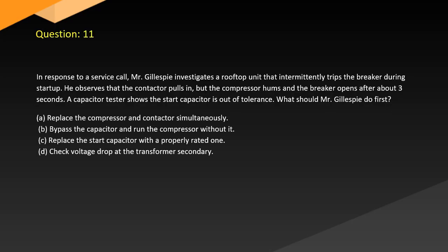Question 11. In response to a service call, Mr. Gillespie investigates a rooftop unit that intermittently trips the breaker during startup. He observes that the contactor pulls in, but the compressor hums and the breaker opens after about 3 seconds. A capacitor tester shows the start capacitor is out of tolerance. What should Mr. Gillespie do first?